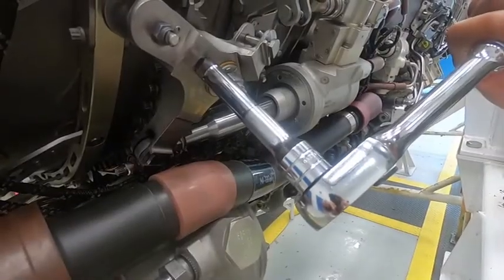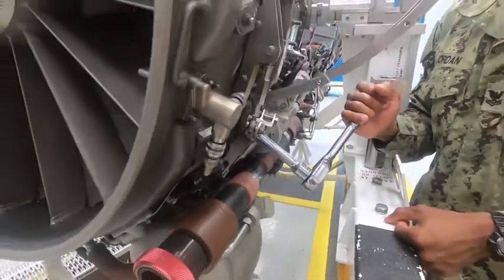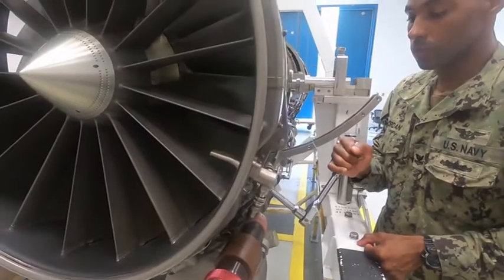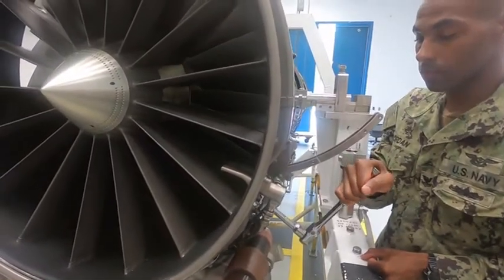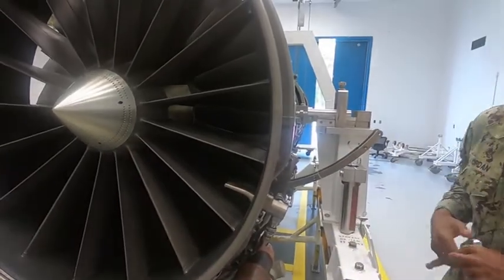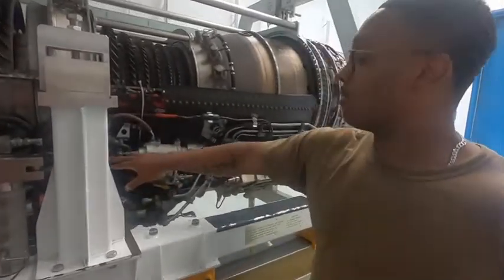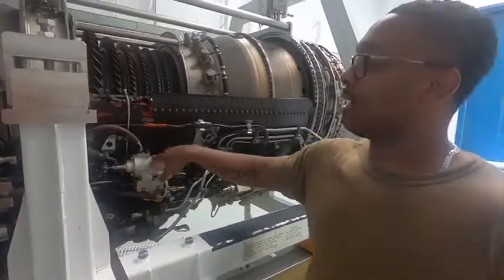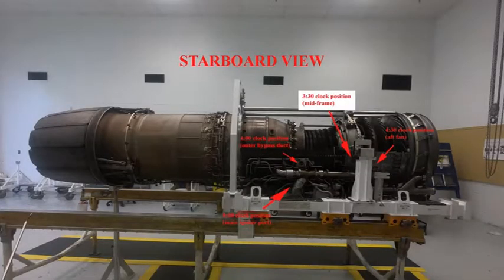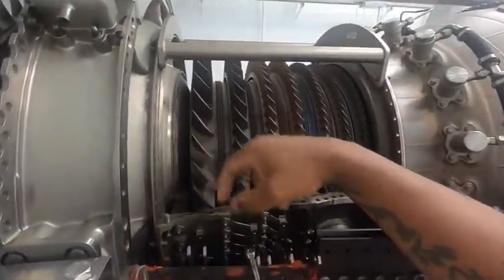Before beginning the borescope inspection, we will need to fully open the FVGs and the CVGs, which are the fan variable geometry actuators and the compressor variable geometry actuator. The purpose of ensuring that the CVG actuator is fully closed is that when we borescope through the mid-frame port, looking aft, we will be able to fully inspect the first stage compressor blades.